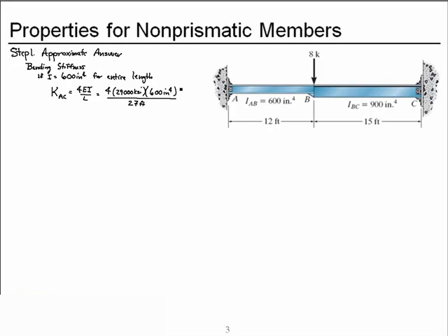We have mixed units. Let's make the numerator feet instead of inches. We have inches to the 4th over inches squared, so the numerator is kip inches squared, and so we'll square our conversion. Put these together, we get a bending stiffness of 17,900 foot kips for member AC.